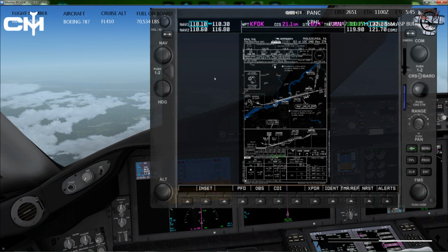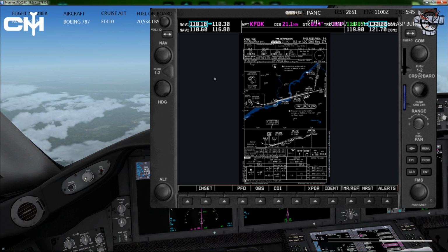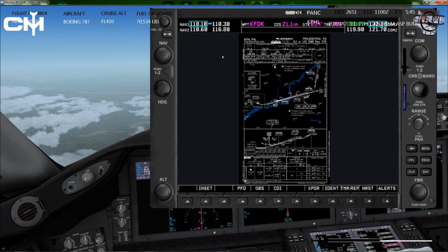Okay, after fumbling my way a little bit through the arrival briefing a little while ago, hopefully we'll do a little bit better on the approach briefing. Our wind is looking to be about 300 at 15 knots, so we're going to be using runway 27 right. It's going to be the ILS for us today, because why not? The ATIS is going to be on 133.4, approach on 124.35. The tower for us is going to be this guy here, 118.5.